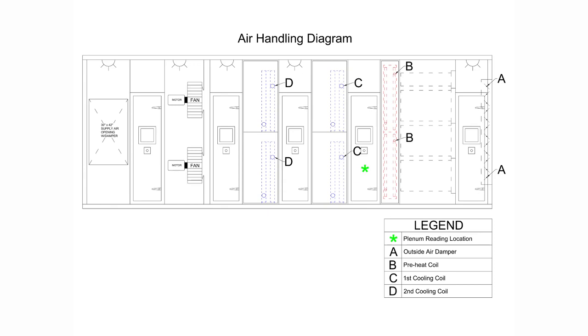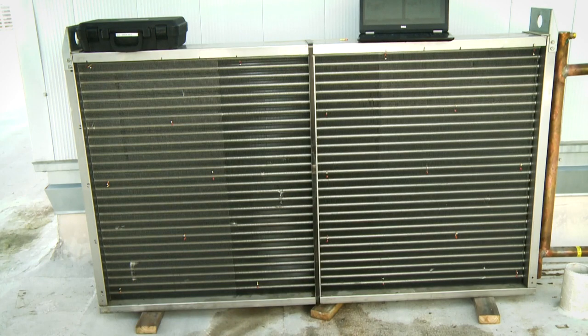The preheat coil B was selected because the chilled water coil's isolation valve would have to be closed to test a dry coil, which was not allowed on a 100% outside air handling unit. The preheat coil consists of 2 stacked coils, top and bottom, requiring both coils to be tested with 38 readings. The demonstration coil has identical dimensions as the preheat coils.